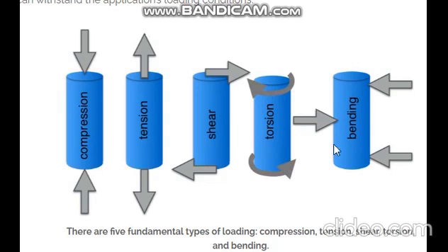And here, if this is the machine component, if one force is here in the center and there are two forces on the other side trying to push it this way, then what happens is bending. So this is a kind of bending loading.